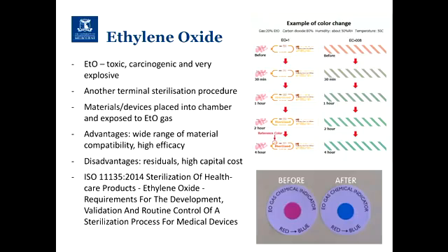I've also put these indicators. While I said you can do batch testing to see if your ethylene oxide or your sterilisation procedure has occurred properly, you can put these indicators in with whatever has been sterilised to make sure that it has been exposed to the conditions.